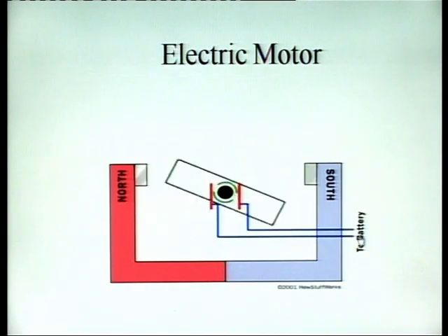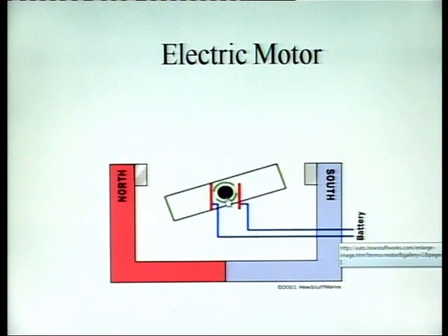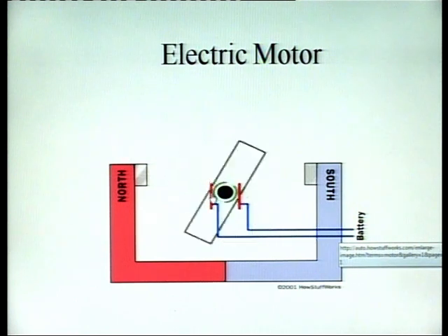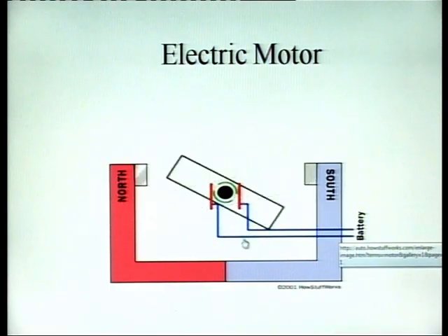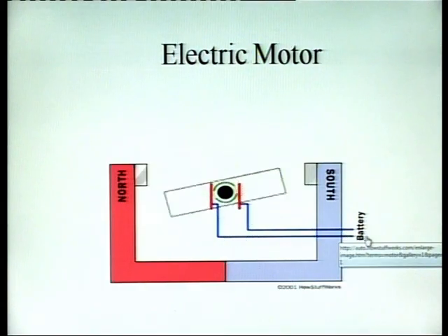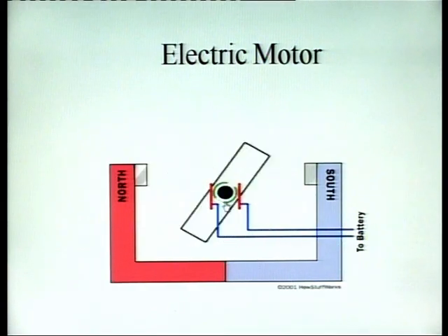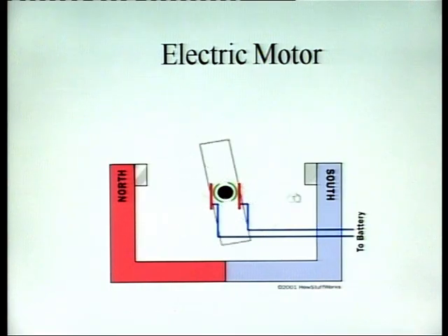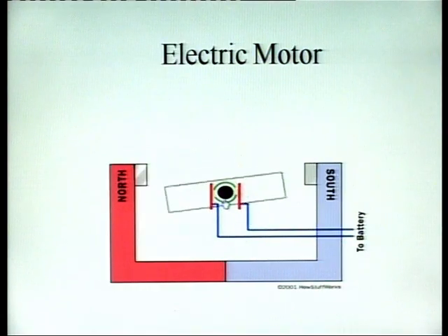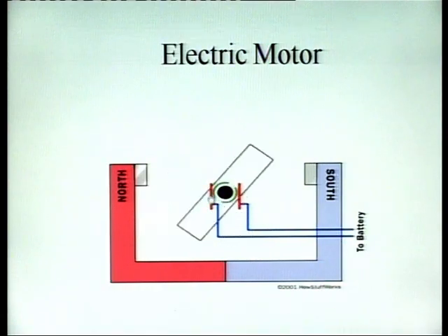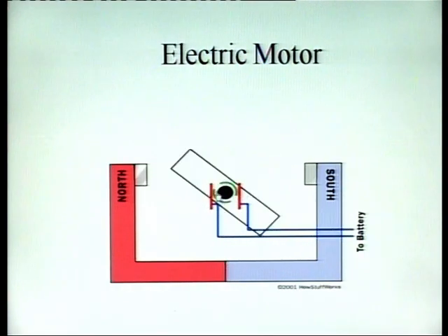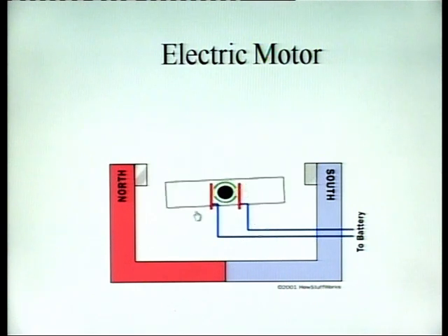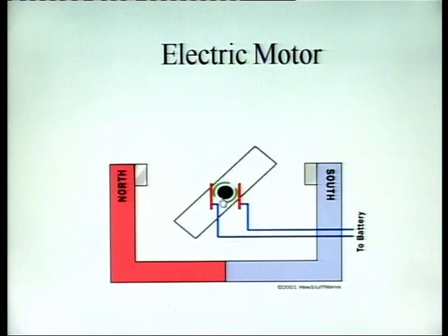Here you can see the rotor is rotating. This red line, which is the brushes, is not rotating. They are used to carry the current to the rotor winding. So, from the battery to the armature winding, these brushes help to supply the current to the rotor winding.